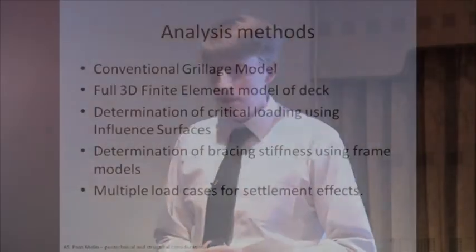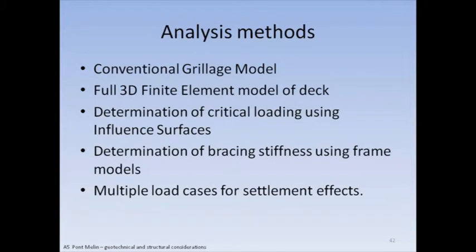Adequately go across the deck with flanges staggered as the cross-section goes through. So to undertake the analysis, the conventional way would be with a grillage model, but it was also decided that a three-dimensional finite element model would be carried out to be able to look at the interaction between the deck slab and the beams in a bit more detail for this possible settlement and build-up of stresses within the structure.